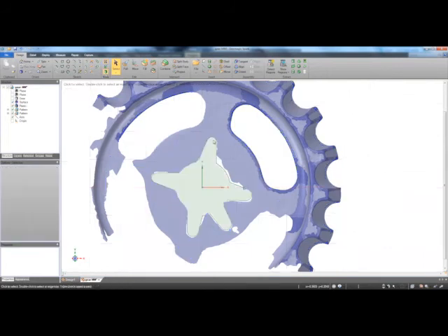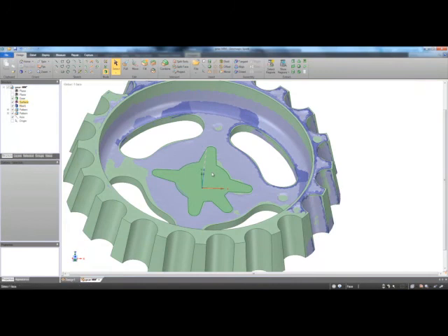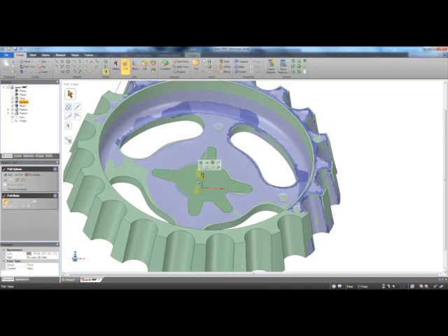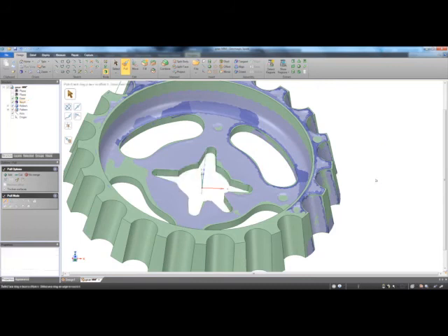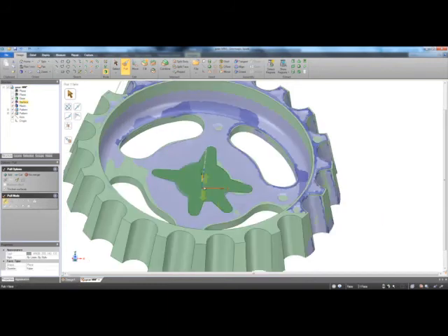I'll go back to 3D mode. I'll show the gear, and you'll see that that sketch is on this plane. So if I go to pull mode and click on this face, if I just drag left mouse button and drag down, it goes ahead and cuts away of that CAD model. So I'll undo that real quick and just show you again.